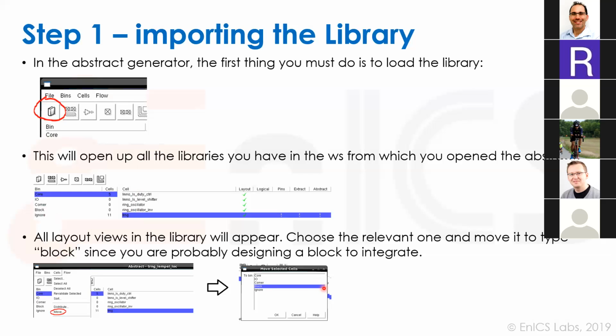So Odem, you said something here, just a little bit of background about that, and maybe Slava will help me with this. In your LEF, you have a class. The first thing that it says about each cell is which class it is, and there are classes such as core, block, and maybe some other things. That is a difference between, for example, standard cells or other types of macros. And this causes all kinds of things when you're doing special routing or just general routing. The Cadence tools really use this class core or class block to decide what they're allowed to do. And if it has the wrong word, it just won't work, and you really pull your hair out trying to figure out why.